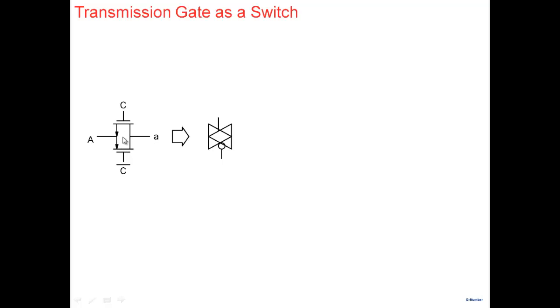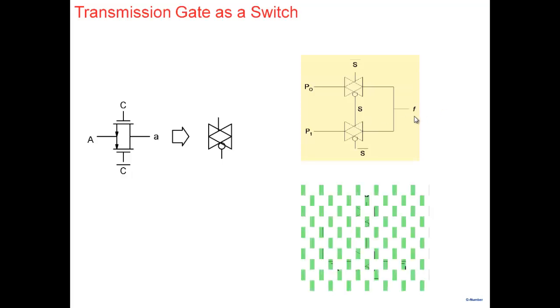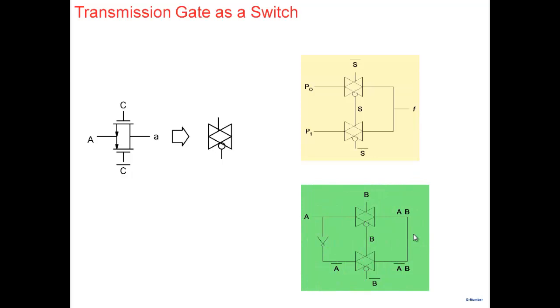So with that, it's a good switch, and with this transmission gate you can implement the different logic that we saw earlier. So for example, you can see that this forms a 2:1 mux here. And you can similarly verify what this particular operation is, AB bar and AB, so you can check it out. So you can implement things in this particular manner here.